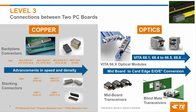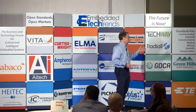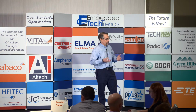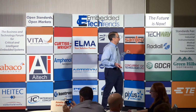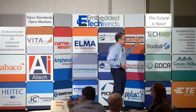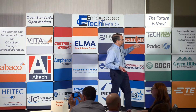You can see similar trends in stacking connectors, where you started at PMC, and today you're up to FMC and FMC plus, and others spoke today about some of the technologies coming to bear there to increase the speeds through those connections. If you look at the systems that have those embedded transceivers on them, you can see how that's kept pace with the evolution to parallel transceivers.